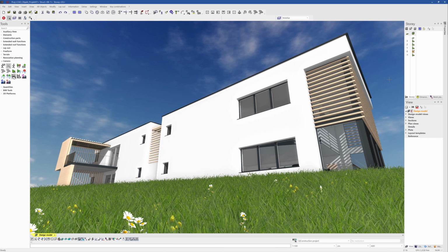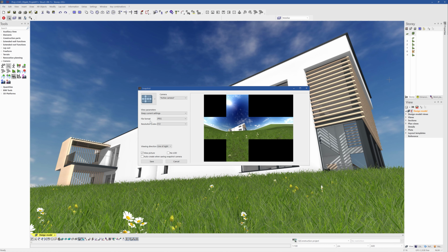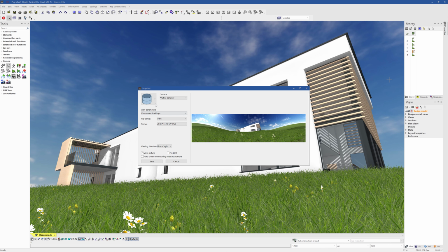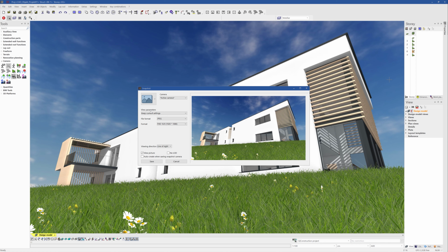If you want to take a snapshot or a picture, you can simply activate the corresponding function. Here we can find the set parameters. You can choose the format of the snapshot, cube map, panorama or 360-degree panorama. In our case, we keep the snapshot here to create an image. We now select an already saved position, it's camera position 1, and would like to create an image with a 4K UHD resolution with a file format PNG. When the parameter mask is confirmed, the desired image is automatically rendered.